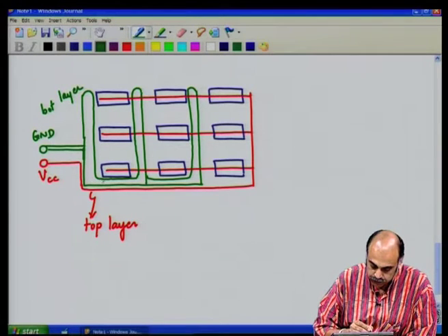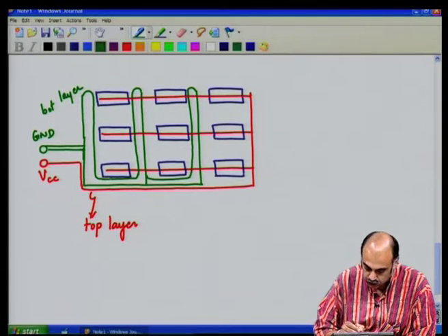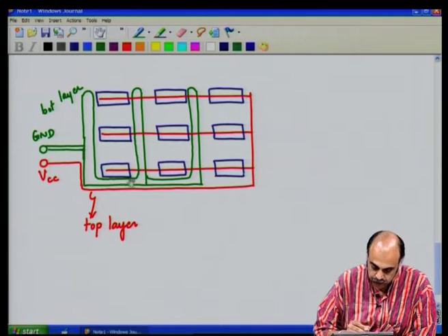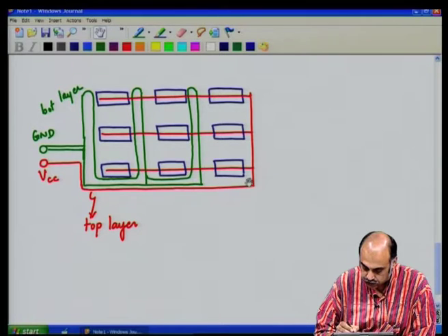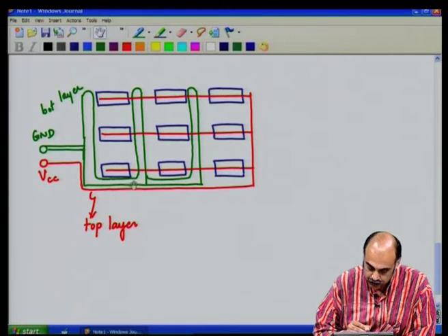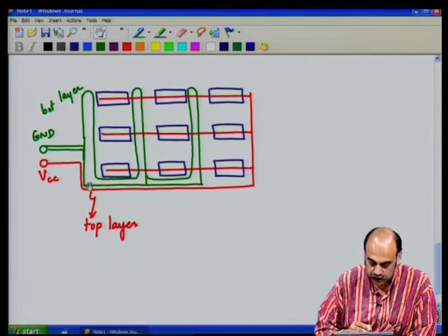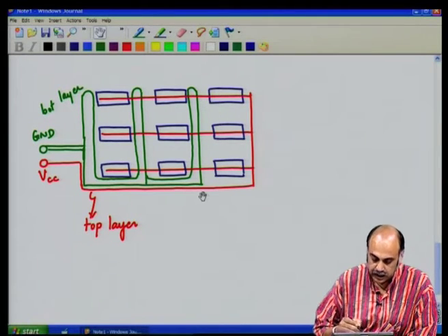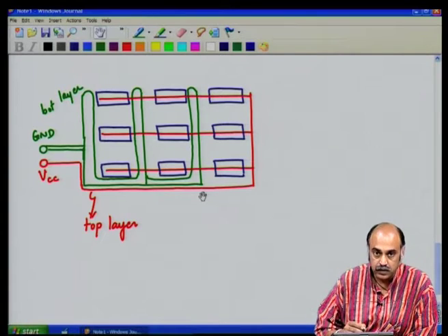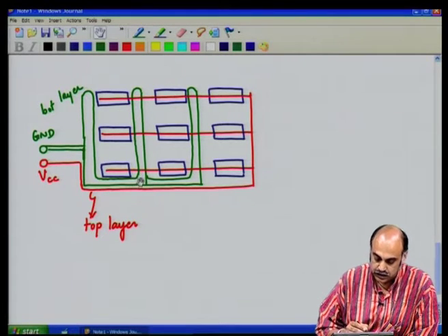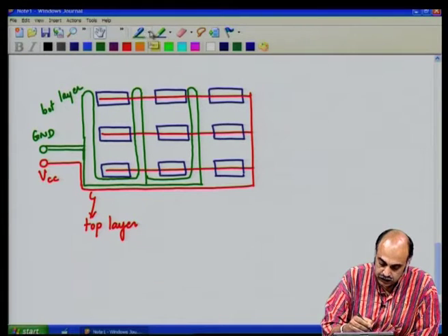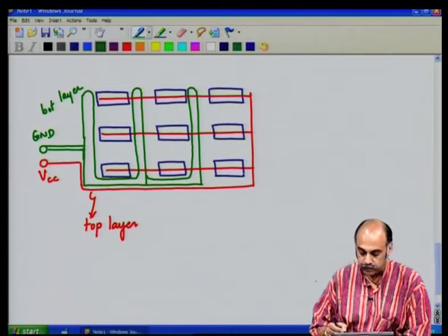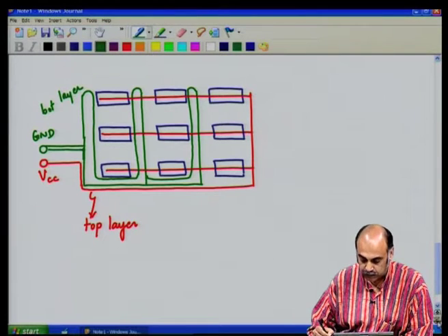Now, by trying to keep the majority of the ground and the supply in this zone, you can make the ground very thick, and then the supply on the top layer overlaps on the thick ground layer, so that you can have a good level of distributed capacitance at this portion. So that each of these lengths will have some capacitive impedance here to supply the spiky currents. So, this is one type of ground routing which is very common.